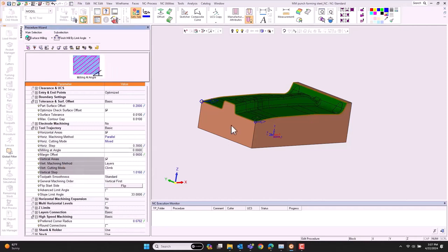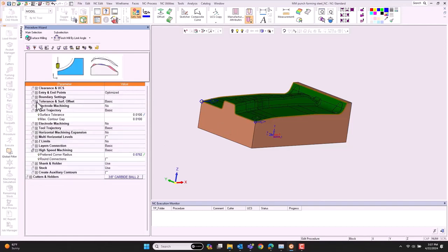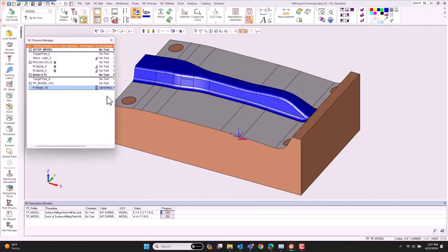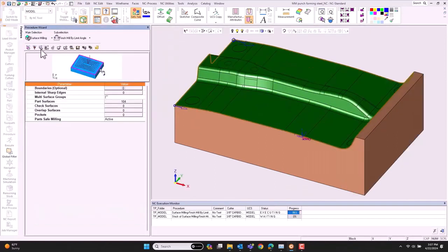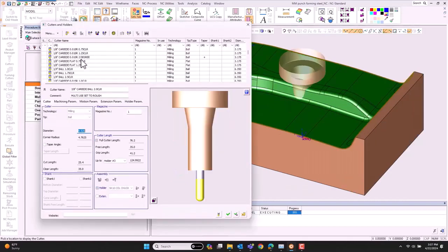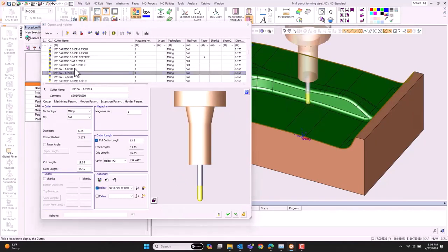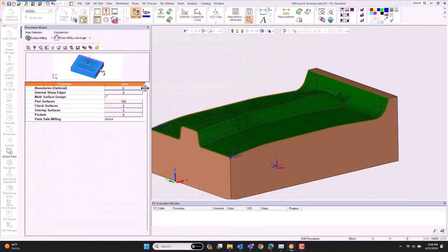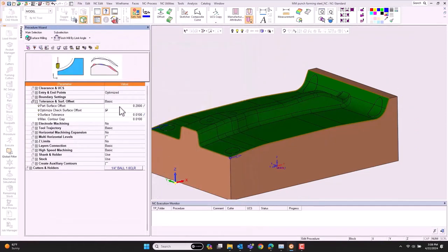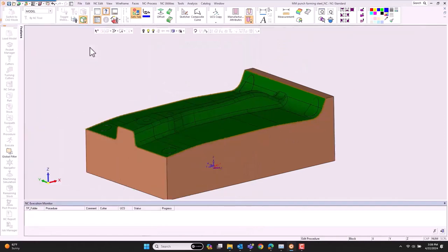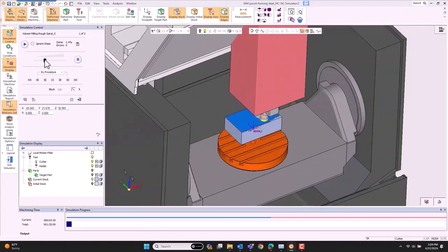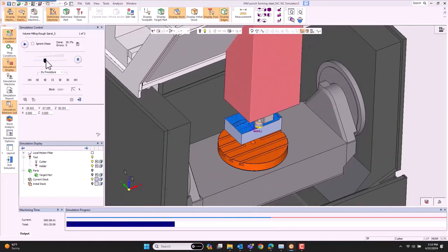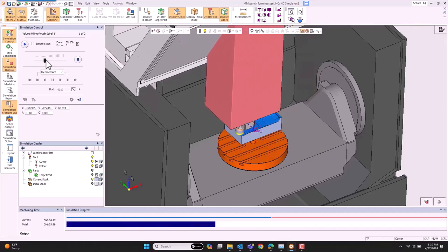Here we're doing a finish by limit angle. So as it creeps around, like 45 degrees along a fillet, it can transition how it goes about cutting it. So maybe it lace cuts the top flats, but then Z levels those taller sidewalls. Each of these can be controlled too with the size of the tool length. So perhaps I'm starting with a shorter cutter because I want to have more rigidity and I can cut quicker. But then as I get into longer areas, it won't reach. So the system knows enough to then change over to the longer tool that happens to have a different speed and feed.